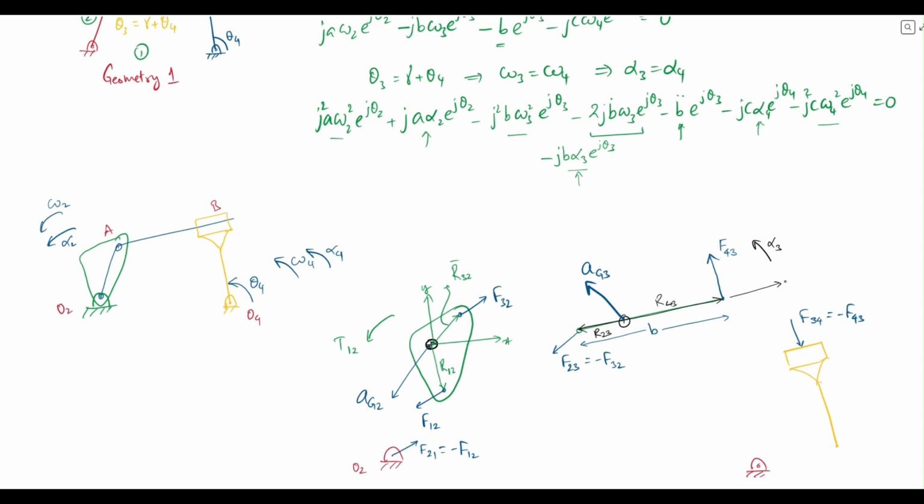We can write a unit vector along this direction. For instance, we can say U hat is along the link. That would be the axis of slip. And the force F3 has to be perpendicular to that axis.